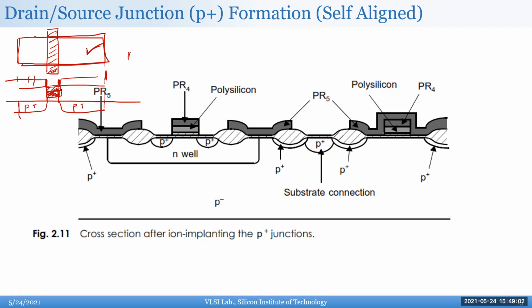You actually use the same polysilicon you use for the gate, but instead of using it on top of a diffusion, you just connect from one end to another end, and you get a resistor basically. Okay, I hope that answered your question, Prachita.